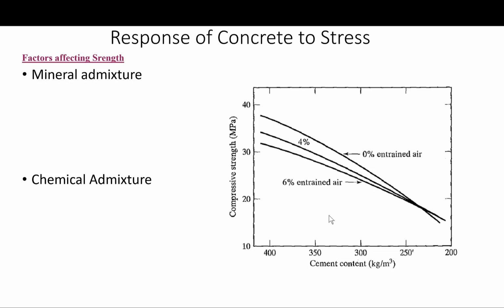But water-reducing admixtures, especially superplasticizers, may provide an increase in strength even at the same water cement ratio, due to greater cement hydration resulting from improved dispersion of the cement particles and the elimination of the large pores that may act as internal flaws, if you remember.